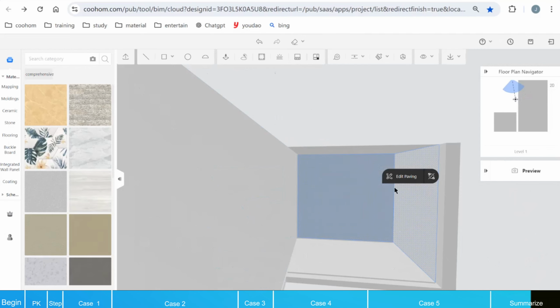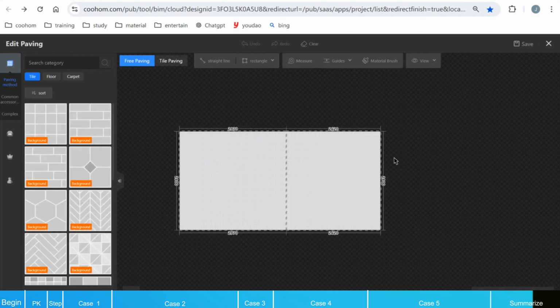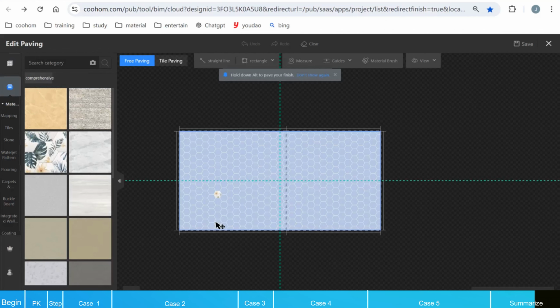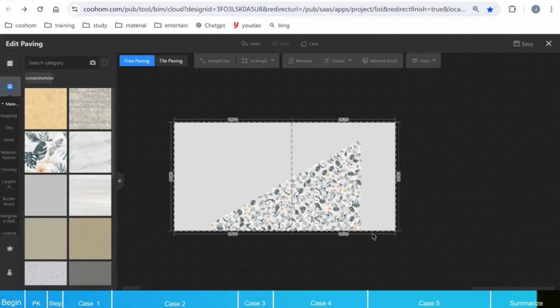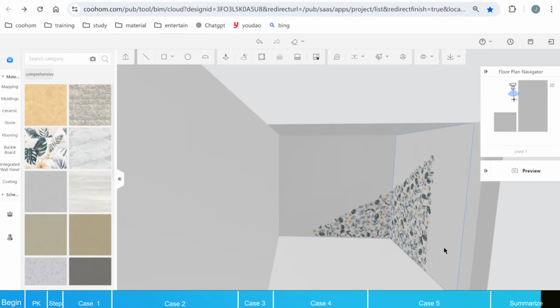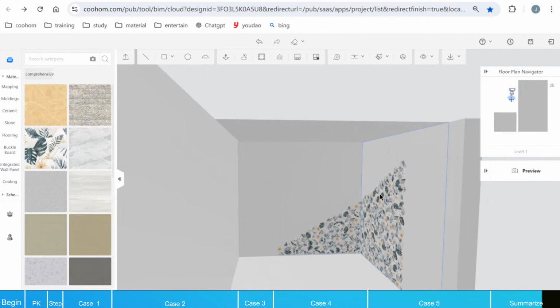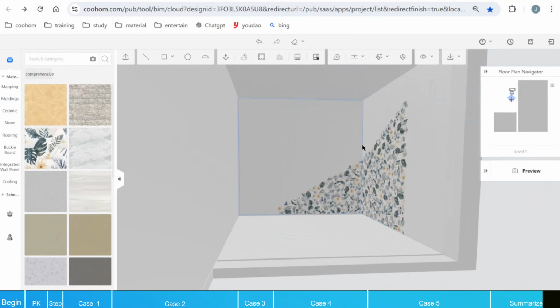When you click connect face, and then you go into the added paving. So you can see this wall just connects together. So you can create some complicated paving method in here and click this one. You can just drag and pave. So you can see our bricks just pave into different walls and they make these patterns continuous. Okay, so we can go back. So in this corner, we have these continuous patterns on these two different walls. Okay, so that's what we can do in our material component if you want to create two continuous surfaces.